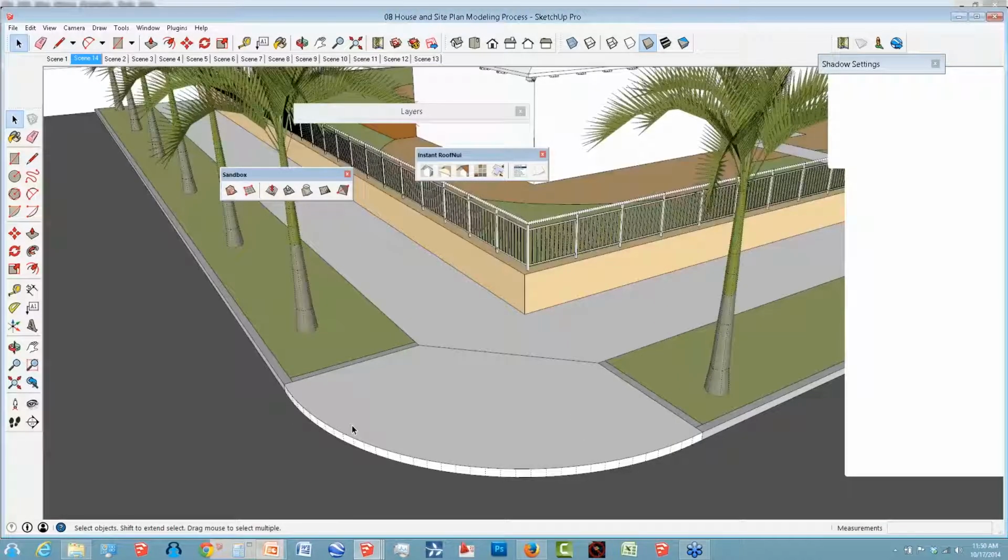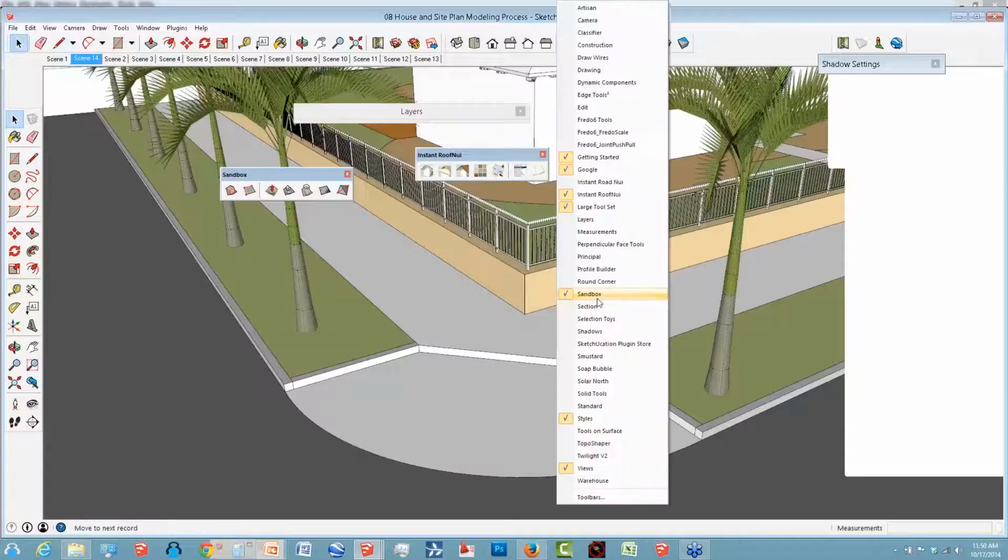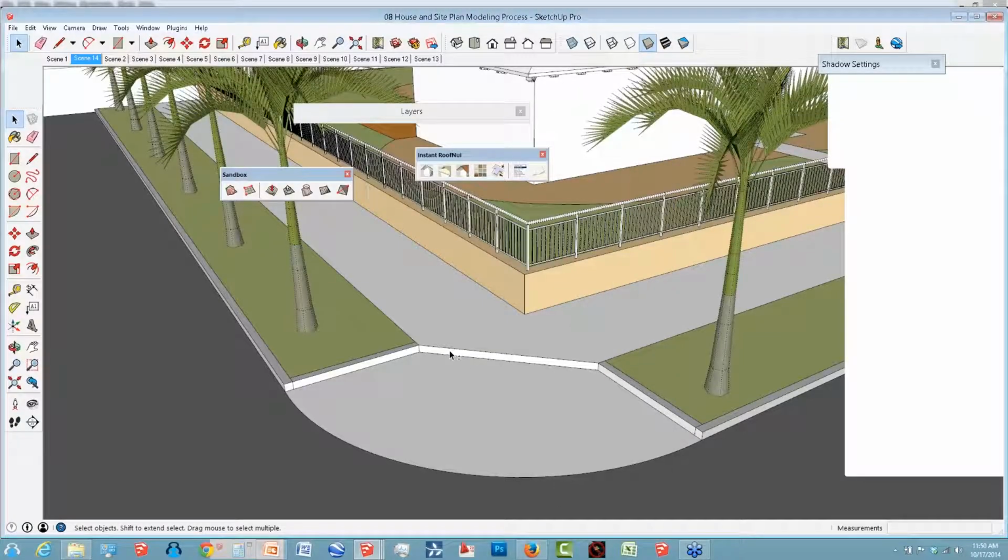And the sandbox tools, if you right-click on SketchUp, they're part of the free version as well as the pro version. They're called sandbox. I'm right-clicking on them right now. You'll see it in the tool menu here. And I can simply select this edge, and I can select this top edge as well. So this is like my bottom of my grade, my top of my grade. That's essentially what it is, and that's what grading in SketchUp really is.